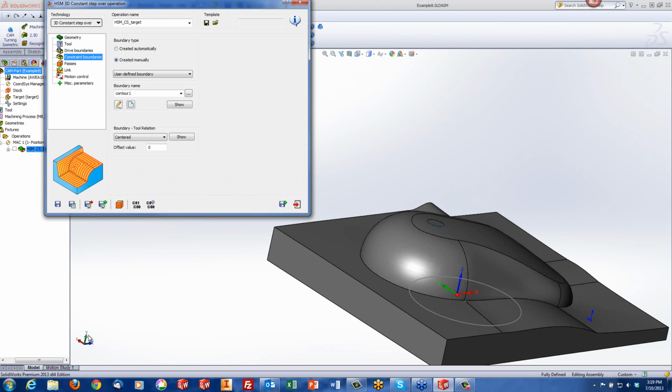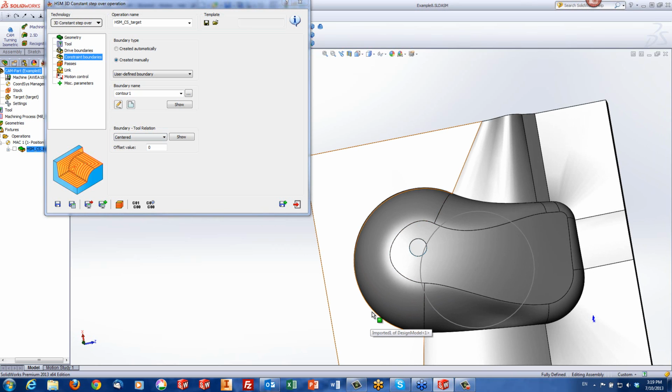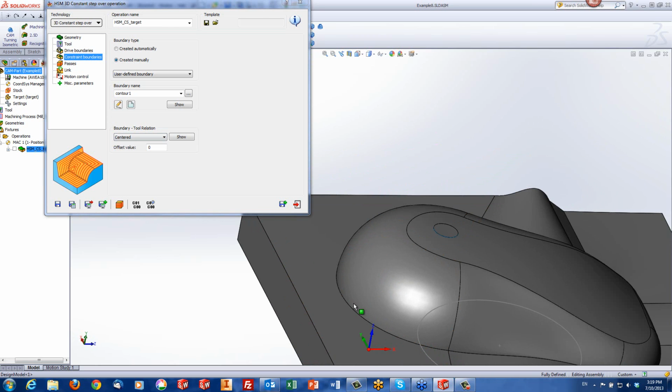The reason for that is simple. Taking a look at our constraint boundaries and our dry boundaries, more on our constraint boundaries in fact, we have the tool going to the center of our boundary. So if it's going to the center, when I'm standing in the center of the tool over this, it can't go past the center of the tool, so therefore it can't go further out. And because of that, it can't go further down on the part as well.